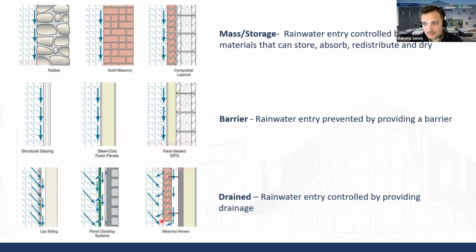And then there's this exterior shield blocking wind-driven damage, as well as blocking about 98% of the rain from getting into this system. The air cavity, which is integral to rain screens, allows that last 2% of water that gets through to condensate on the backup wall and, through gravity, be carried down to a weep hole at the base of the wall. It's a redundant system. It's shielded. It's going to last the test of time.